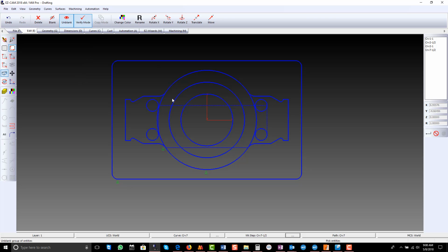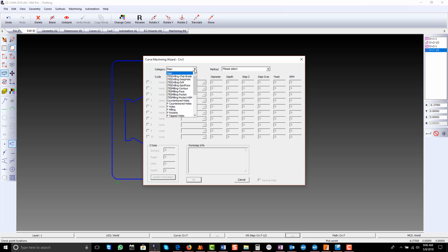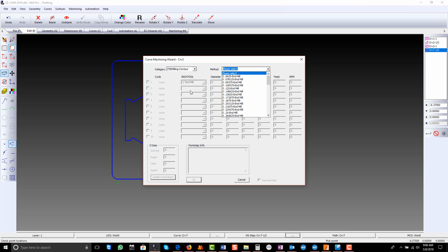Then we're going to go and double click here. I escape, double click, and we'll go back to milling a face, 1 inch. Let's change things up a little bit here. Let's go back, we'll contour, we'll use a 1/2 inch tool, and the depth we'll say is 1/8.